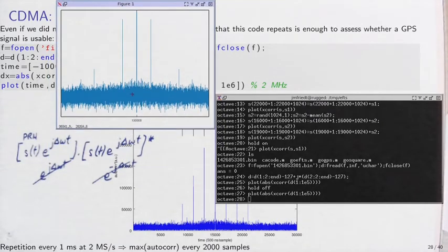data set, and I see now that this side lobe, visible on the bottom left corner here, is located at 98,000. This is located at 102,000. So we have cross correlation side lobes at minus 2,000 and plus 2,000, which at a sampling rate of 2 megasample per second indeed means that we have side lobes at minus 1 millisecond and plus 1 millisecond, and then we've got the next ones over here, that's 94, so we have all these additional side lobes.